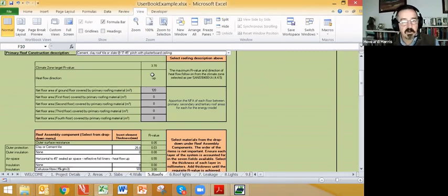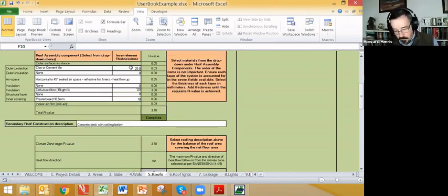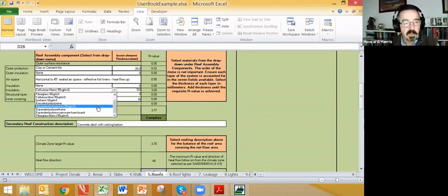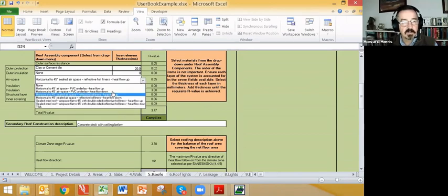So 3.7 R value is required, and we then need to check and see whether, let's say, a 20 millimeter tile in conjunction with 120 millimeters of cellulose fiber, or perhaps we could use the drop down and find a similar performance fiberglass insulation, is contributing an R value of 3 to the total R value. We have also a reflective foil plus air spacers in situ in this design.